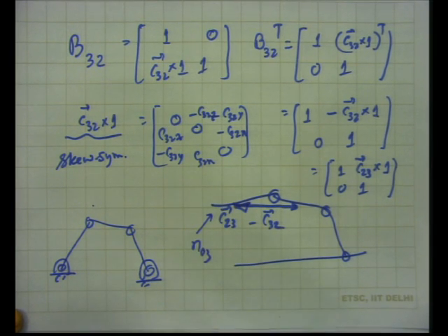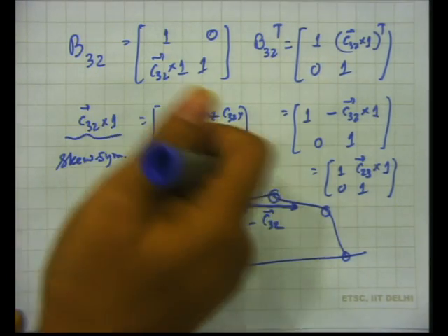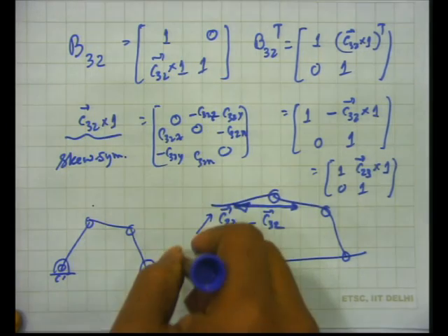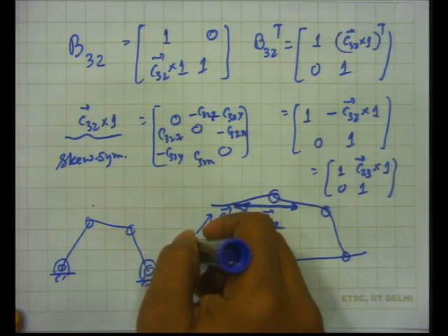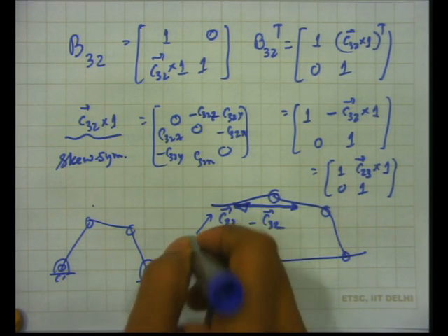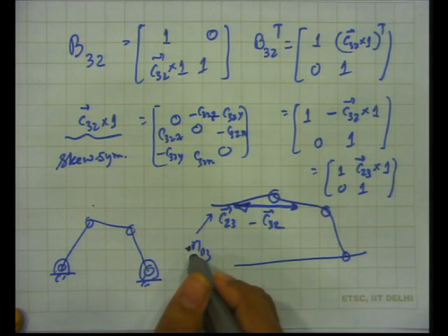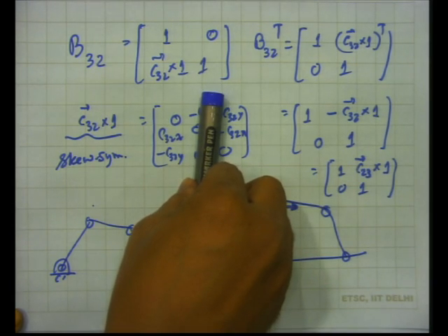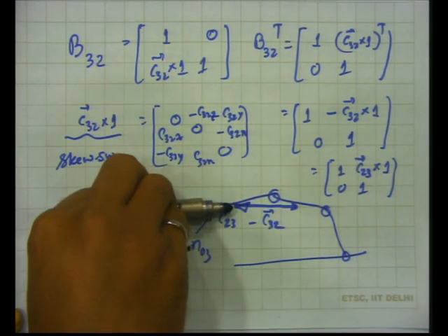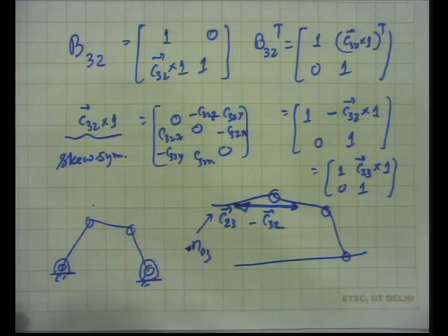So, for such a planar system n 03 has a component about the x direction or this direction, okay. But E 1 is perpendicular to both of them. So, E 1 transpose n 03 will obviously be 0 because E 1 is the axis perpendicular to the plane of the motion and n 03 are the reaction components about x and about y, okay, because about z there cannot be any reaction because it is allowed to move.